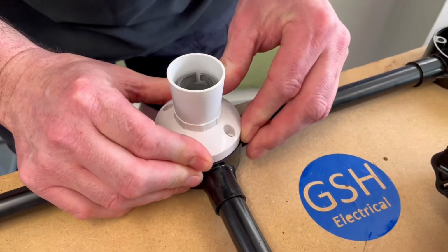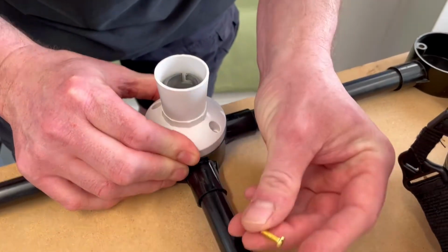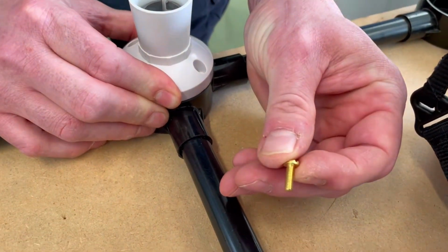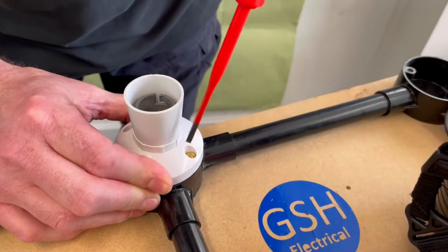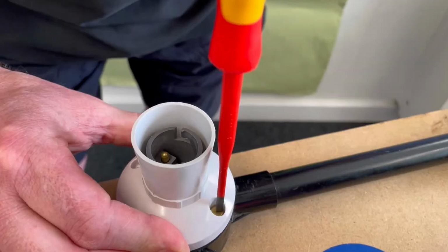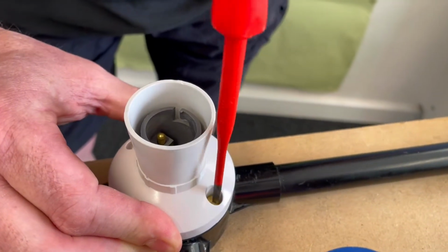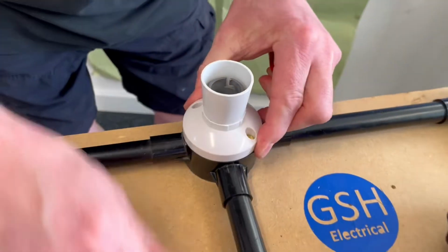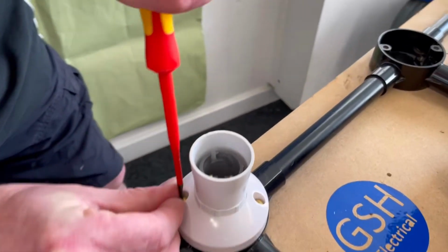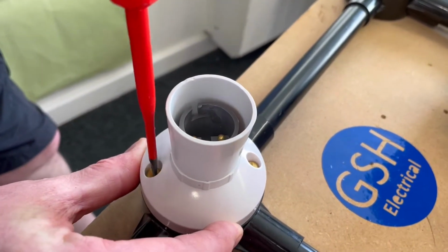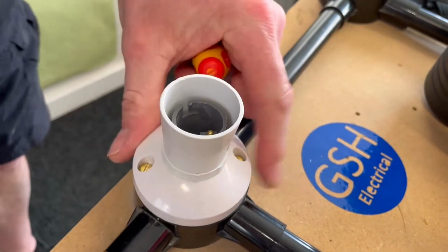I'm going to find my M4s, and these are here, these brass M4 screws, in order to hold it in position. So it's important that we use the right ones. Too many times I've heartbrokenly seen someone using a wood screw in order to secure it into position. So down they go. Locate that into position, and that's my straight skirted batten lamp holder down. So just tighten that one off. So that's it in, so it's in position.